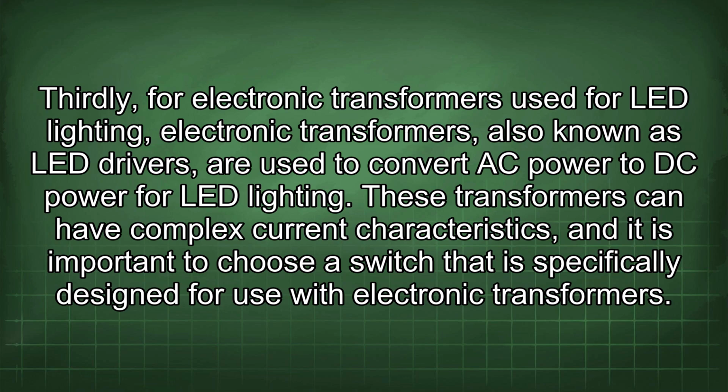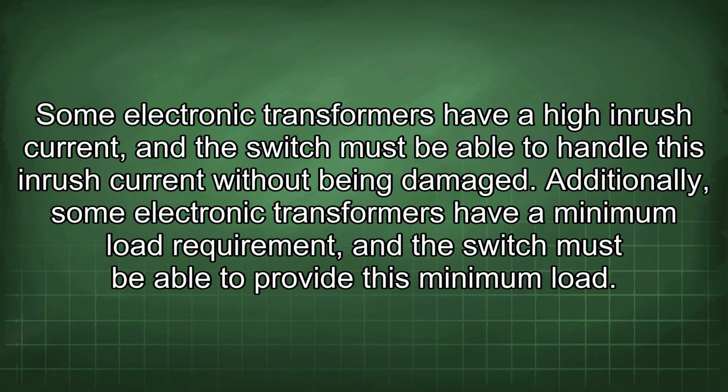Thirdly, for electronic transformers used for LED lighting, electronic transformers, also known as LED drivers, are used to convert AC power to DC power for LED lighting. These transformers can have complex current characteristics, and it is important to choose a switch that is specifically designed for use with electronic transformers. Some electronic transformers have a high inrush current, and the switch must be able to handle this inrush current without being damaged. Additionally, some electronic transformers have a minimum load requirement, and the switch must be able to provide this minimum load.